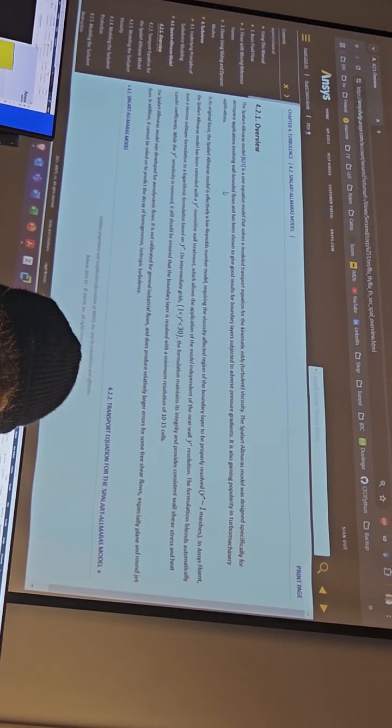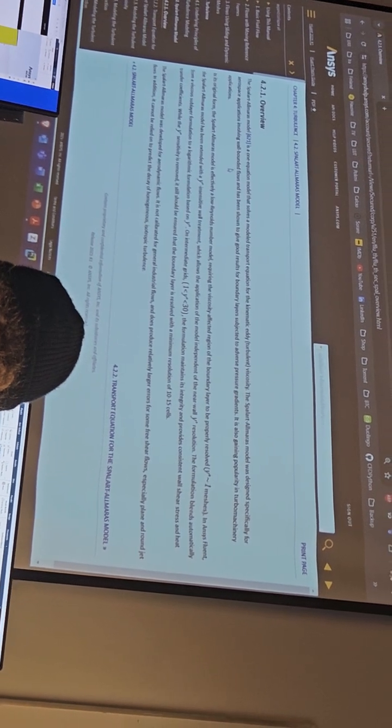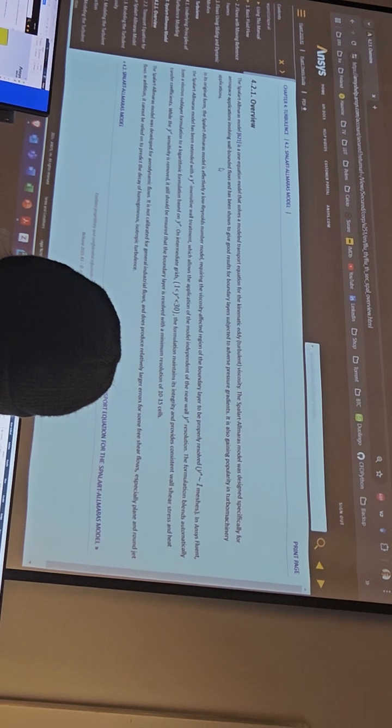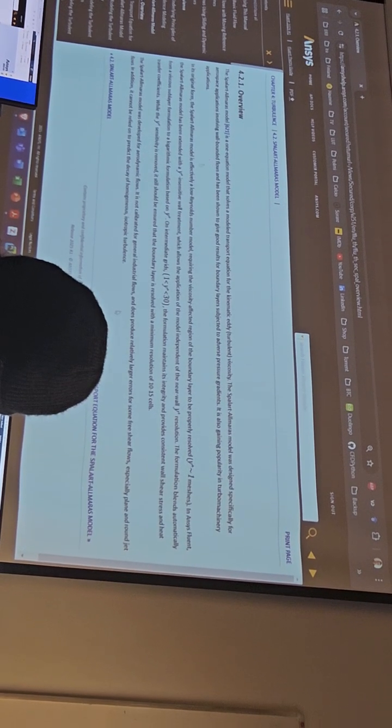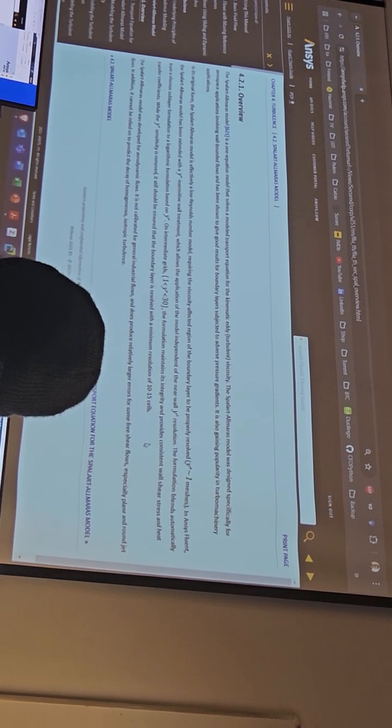Right now, we are not really doing that, so we are taking ready-made grids from online. But it's something that is important when you are choosing the turbulence model, that you are able to solve the boundary layer region. So close to the wall, you need some fine resolution. Here you have some information about what kind of grid you need for that model. And then something that you have seen during the lecture, you also have some suggestions on how you should use this model. So for example, this is quite useful for aerodynamic flows.